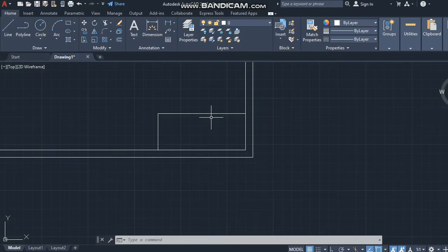Inside this small rectangle that I was telling you, it is 50 by 120 millimeters. That is where we will put our index number, our name, our drawing scale, question number, the school code, the center code, and everything else that the examiner wants. Remember, the examiner cannot mark your work if you don't have a title block on your work. Many people draw the AutoCAD objects, but they fail to put a title block, and so that keeps you going back for more refers until you understand the process of making a title block and incorporating your drawings inside this same title block.